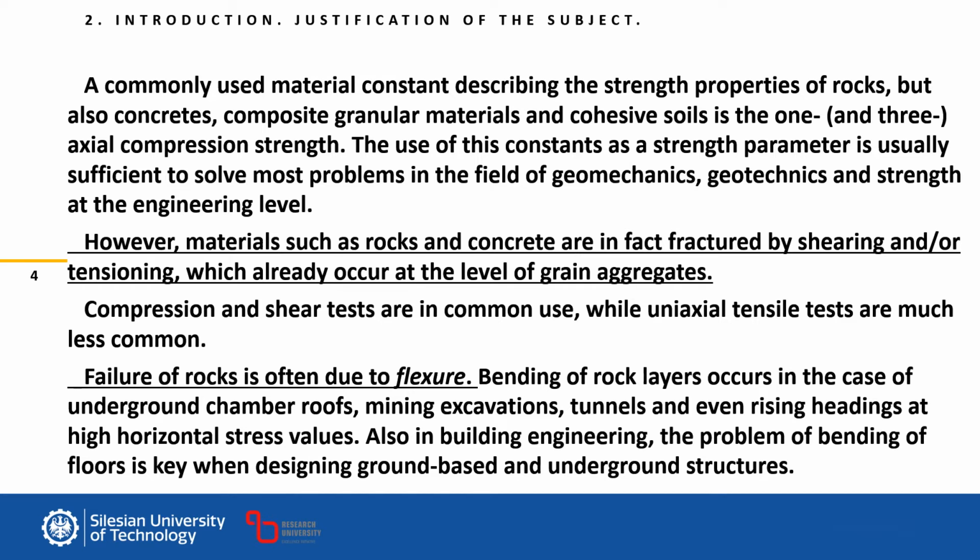However, materials such as rocks and concrete are in fact fractured by shearing and/or tensioning, which already occur at the level of grain aggregates. Compression and shear tests are in common use, while uniaxial tensile tests are much less common. Failure of rocks is often due to flexure. Bending of rock layers occurs in the case of underground chamber roofs, mining excavations, tunnels, and even raising headings at high horizontal stress values. Also, in building engineering, the problem of bending of floors is key when designing ground-based and underground structures.